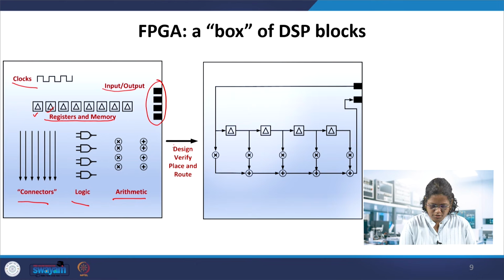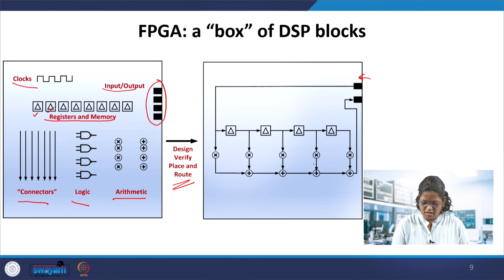So after performing all these operations, if you look at this FPGA, the input, suppose it's taking this as, these registers are delays and this is the input line. The connector is used for this. A connector is picked up and connecting it from the input to the multiplier and registers. These are the registers placed and multipliers and the adders. So often this multiplier also will have another input, which will be the coefficients in case of filters. So multiple inputs can be added to it.